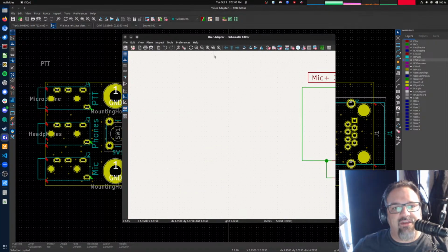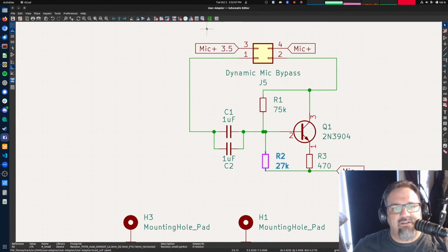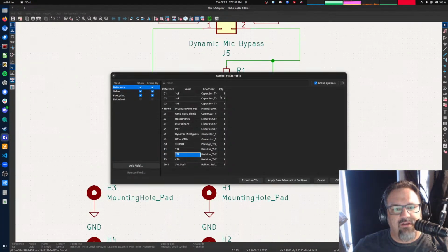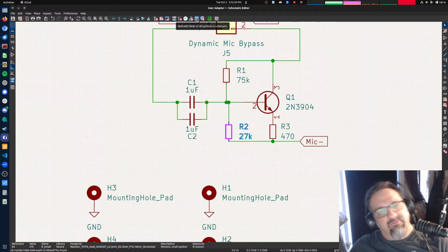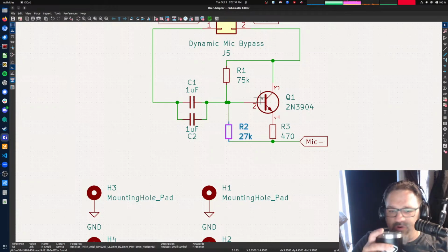I think, did I start putting? I have not. Okay, so what I can do is add columns to the bill of materials in KiCad and include links to Mouser, links to eBay, where to get those parts, and then when you export the CSV bill of materials, great gravy, that'll show up in there.